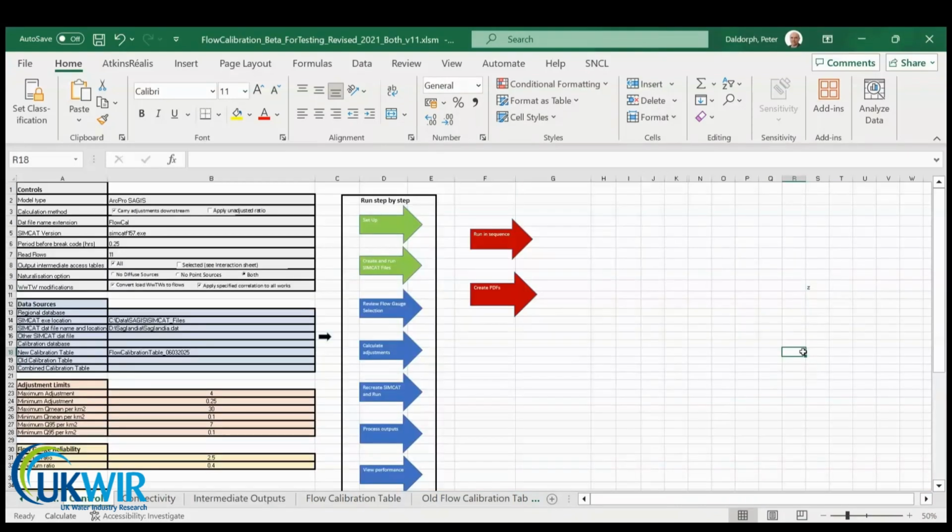We can now go on to the next stage in the calibration process, in this case by clicking on the 4th arrow down, Calculate Adjustments. When this arrow is clicked, the outputs from the 3 SIMCAT model runs that have already been processed and entered onto the sheets are used to calculate the adjustments required to achieve an optimal fit with the observed data.